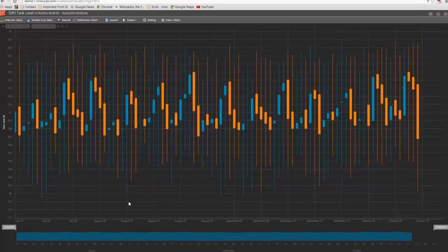So here's information that I've never seen in a SCADA control center, but is very interesting to a lot of people in a water organization. I've got orange lines and blue lines. Again, this is every day during 3 months, so there's 1 line per day. This is telling me, in the thin line, I've got the highest tank level that operated during that day of 23.47 feet and the low of 19.5 feet. That's the range that the tank water went between.